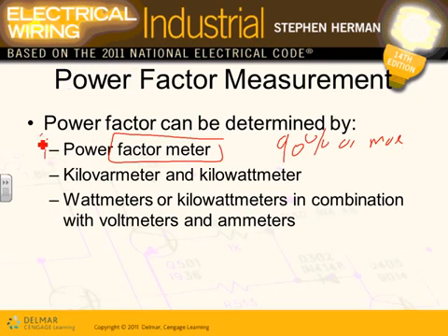So this is probably method number 1 of power factor. Another method, guys, is you can measure the kilovolt-amps and the watts. You have a watt meter, a volt meter, and an amp meter, and you do the calculation and find your power factor. That's not commonly used now.